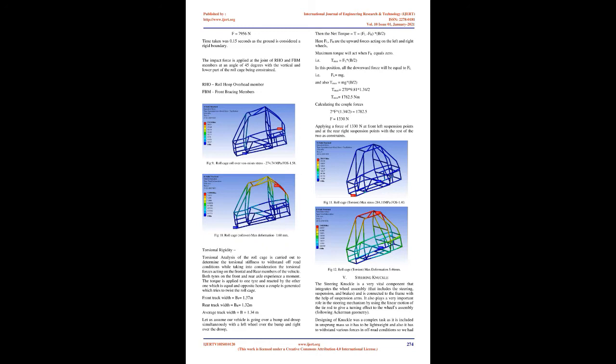During the designing, we took care of each rule given in the rule book, the driver ergonomics, and also the requirements of various domains. In this way, we prepared a basic model of our roll cage, and we used Catia V5 to prepare a driver mannequin and checked for required clearances for the driver. Now the only thing we had to do was certain modifications based on the analysis. After these modifications, we got the final design of the frame.